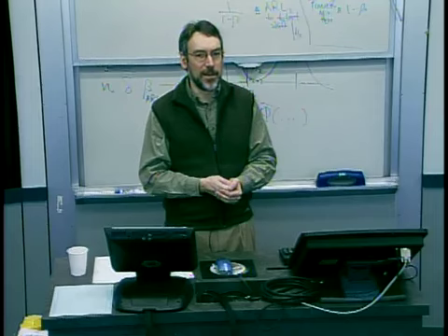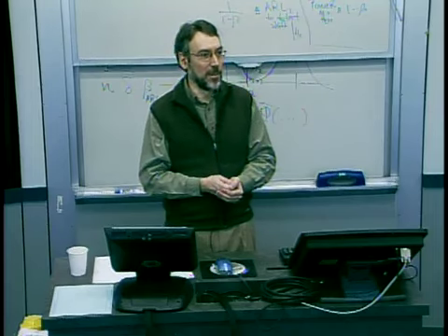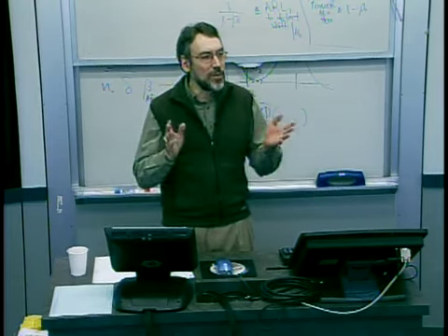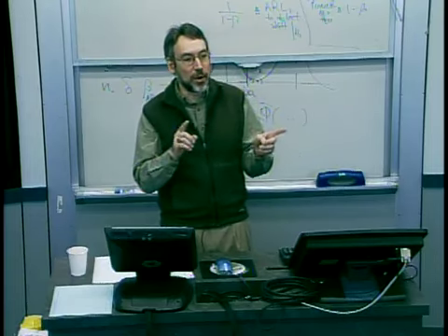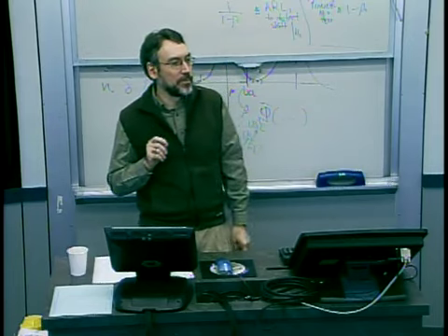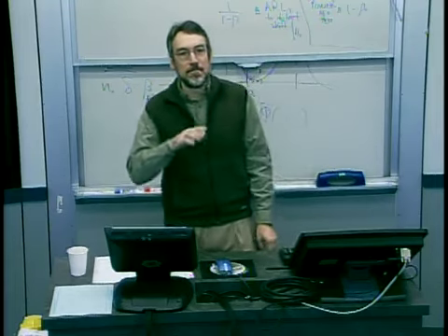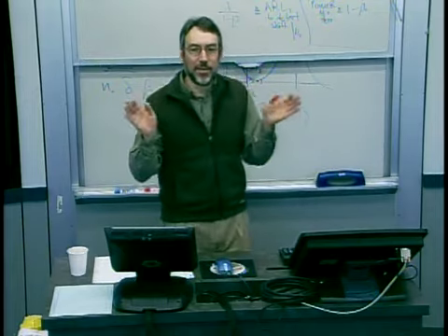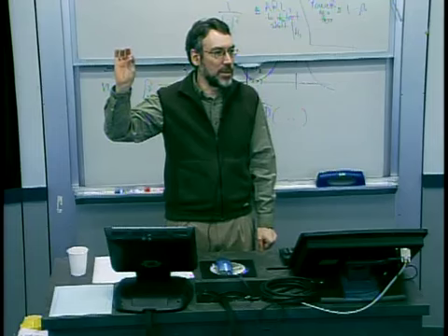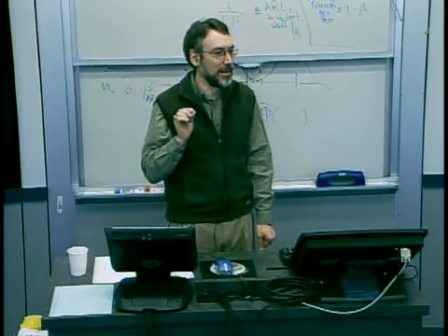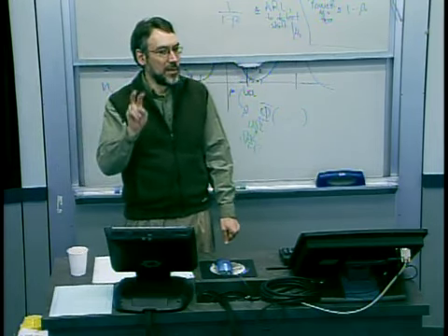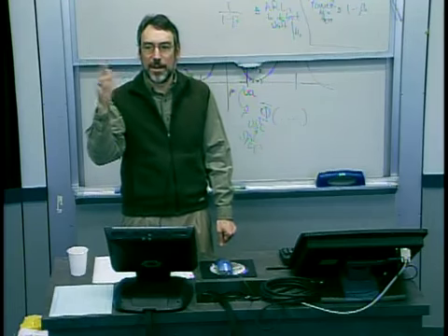And then they wait. They do the next point. If it's also an alarm, then they say, I think something may really be wrong, and then they investigate. What are they doing there? How could you change a control chart to actually do what they're doing? What essentially they're doing is saying, I don't believe the evidence. The 3 in 1,000 chance of seeing one point outside of the control limits is not strong enough evidence for me. What they're really doing is looking for a smaller probability of 2 points in a row being outside of the control chart